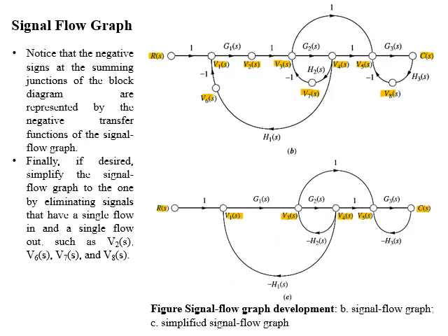Dear students, now after drawing the nodes, we will connect these nodes as the systems are connected to the signals in the block diagram form. The input node is connected to V1(S) with gain 1. V2(S) is connected with V1(S) with branch gain G1(S). V3(S) is connected to V2(S) with branch gain 1.